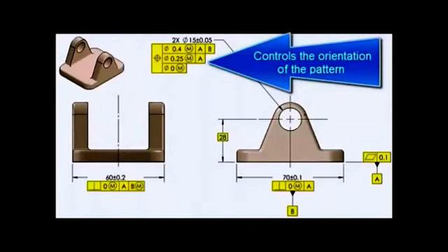The gauge pin is not confined in location to the plane established by datum feature A. It is, however, confined in orientation, or in this case, parallelism. So you're allowed to move the gauge element up and down to find the spot where it will pass through the 2 holes.